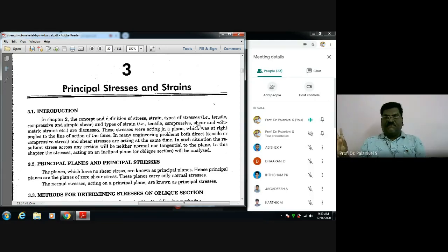So far you know how to compute stress this way, only this much. Is the stress induced in the body uniform in all directions? If you ask me, no. The stress you computed is only in the direction of loading, load divided by the perpendicular cross section. The stress is acting perpendicular on the plane, in the direction of the loading.